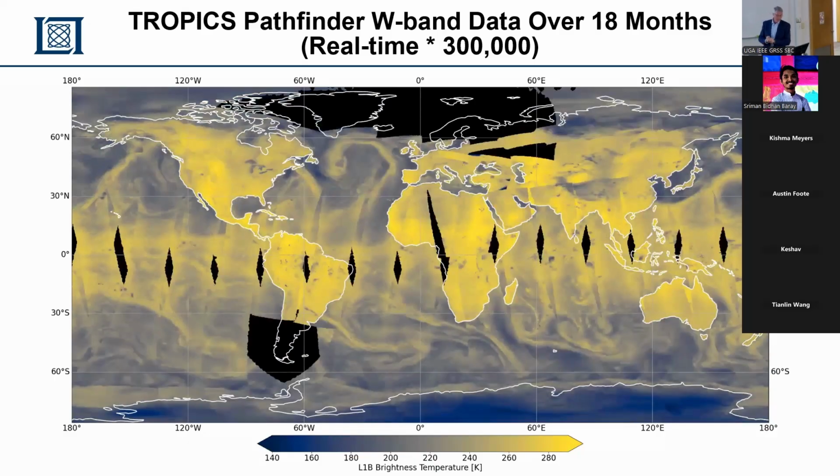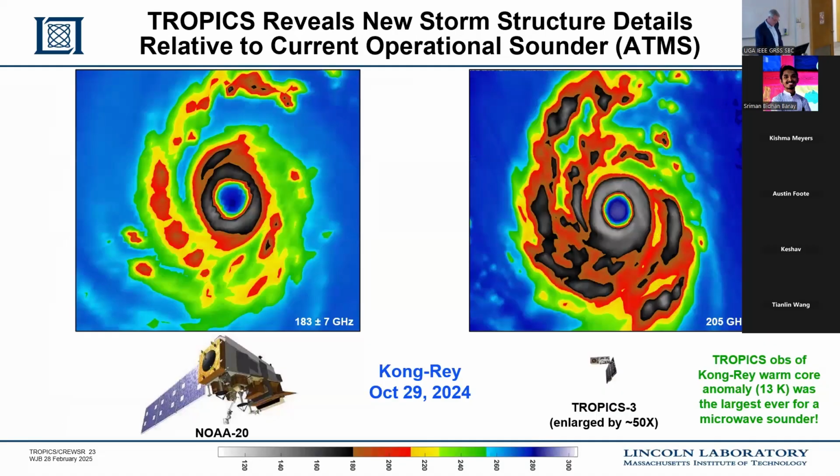The way you design for that, there are two things that you do. One is, if you take a radiation hit, you reboot, right? You just turn the satellite on and off again. That gives a lot of redundancy and resiliency. And then we have multiple SD cards. We've got the constellation, right? So we've got kind of a resilience due to numbers. So we do go offline sometimes. We just reboot and it's recovered. So it's amazing how far you can get with those COTS parts.